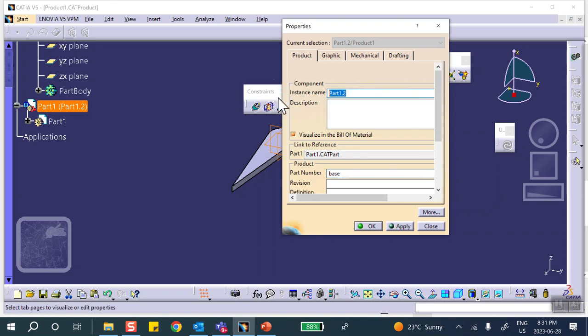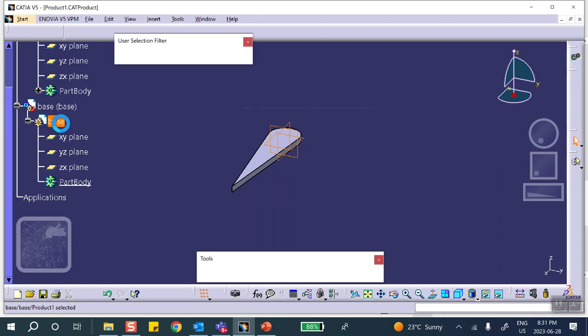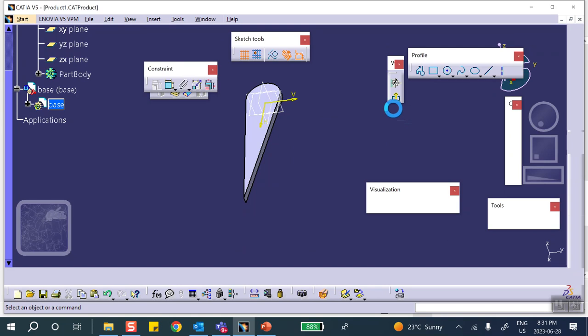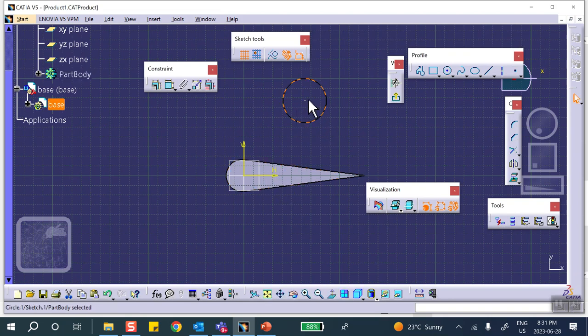And this is the instance name, also base. All right, so let's go make it. Double click. All it is is a cylinder basically. On purpose, I'm going to select this plane, and I'm going to draw it right there. This is going to be the base. Now remember, this arm has to be on that base, but we'll do that.